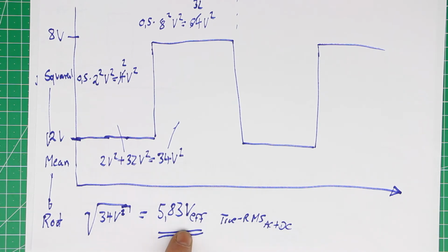With a digital oscilloscope, you of course can also calculate with the math functions the true RMS value. So let's change our setup and let's change the camera to reveal the secret, how the signal really looks and what the oscilloscope says, and what the three multimeters say which is the correct value.